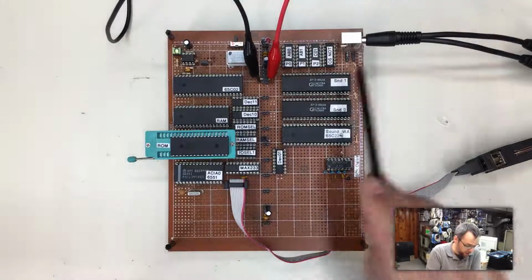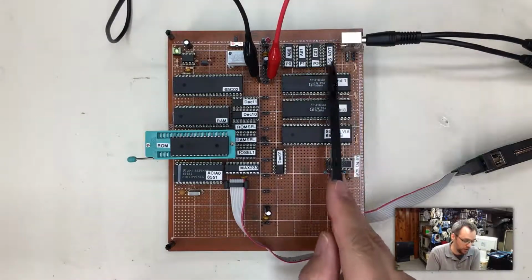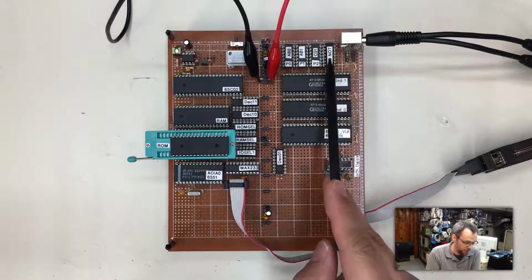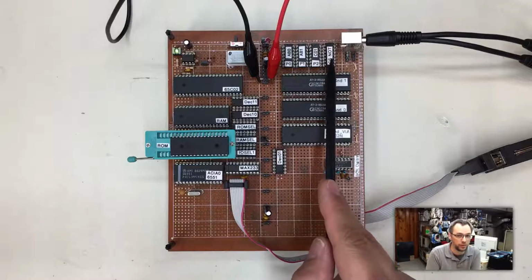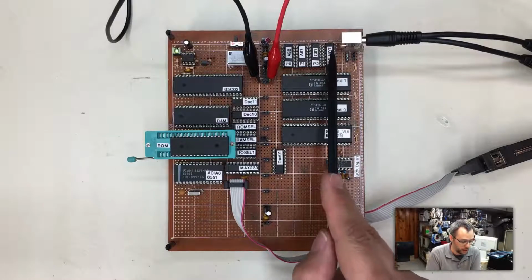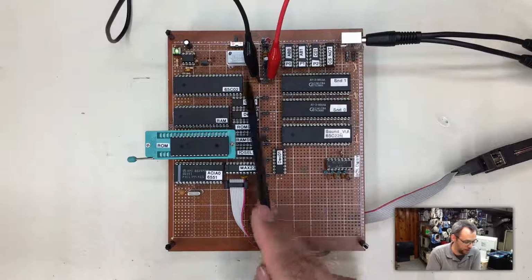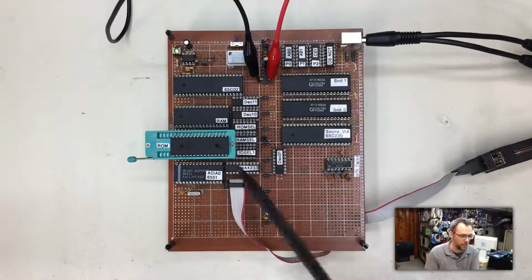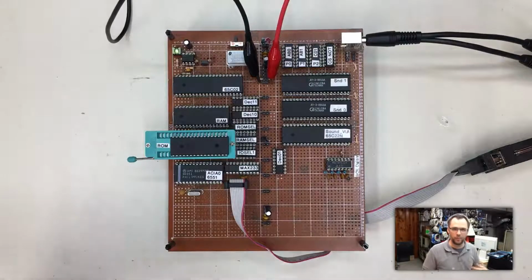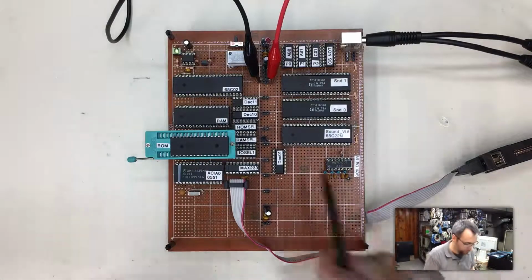However, if you notice right over here, I had to add an inverter chip back in because this is an inverter that does high-speed switching. The thing with this is I'm only using 3 or 4 of the inverters on it. So there are spares, and in theory I can tap this back into the reset circuit at some point and eliminate this. So basically the board is now more expensive than it was before I removed the inverter, because I had to put it all back in anyway, but whatever, we'll come back to that.